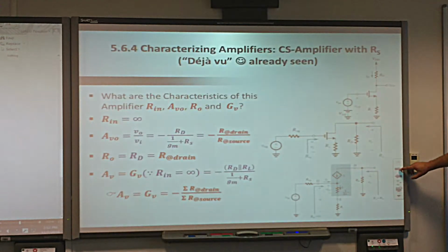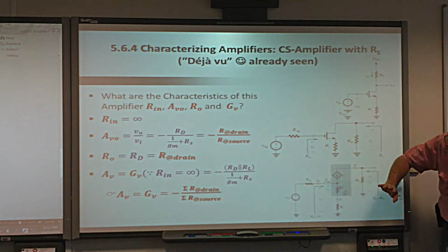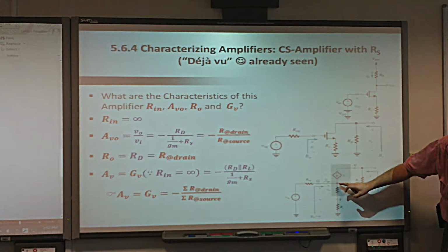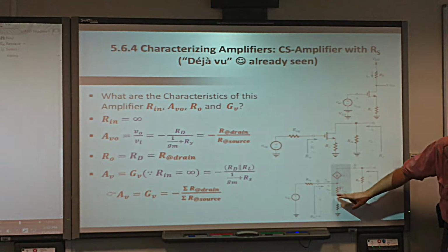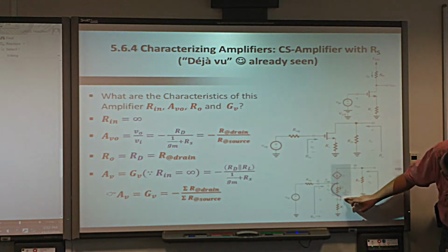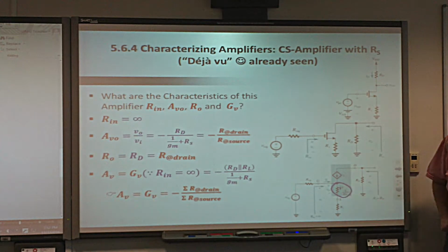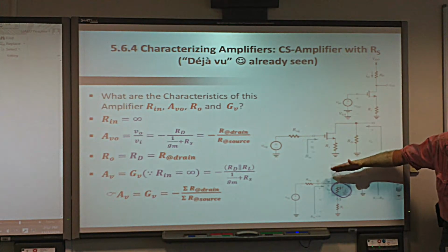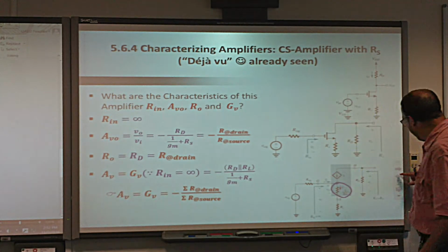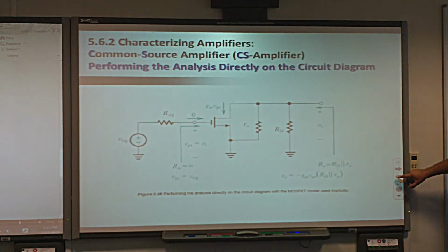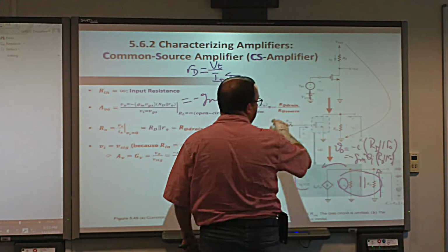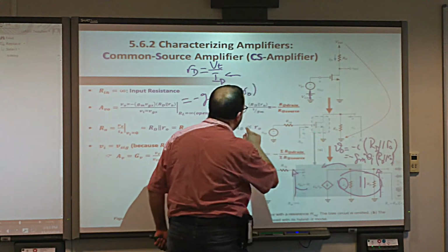This is the T model. No, hold on a second. This is the T model here. You can see that the resistance between the source and the circuit, the MOSFET, we found it before, is actually 1 over gm. So from the source outward, we have this 1 over gm. I will include that in the slides, don't worry. So here, the resistance at the source, we have that 1 over gm.